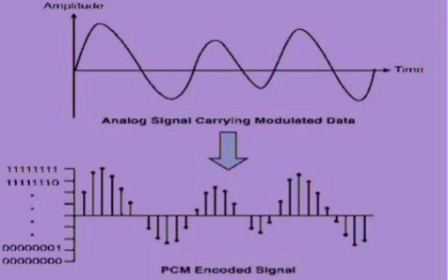Once again, R naught is nothing but the bit rate or channel data rate after channel coding, equal to 1 by T naught. k Tb equal to n T naught, R naught equal to n by k into Rb, that equals Rb by r.